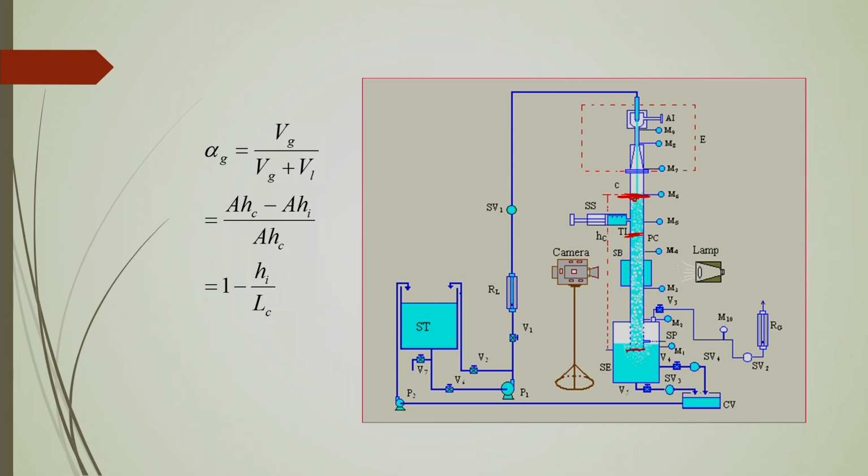That means that after a certain time, all the gas which was entrained into the liquid will be degassing, or disengaging, and the liquid level will come down to a certain height here. So, this will be your clear liquid height; there will be no entrained gas in the liquid.